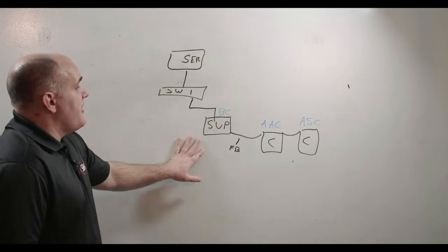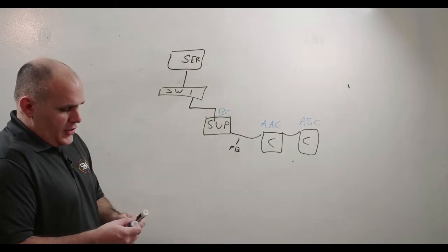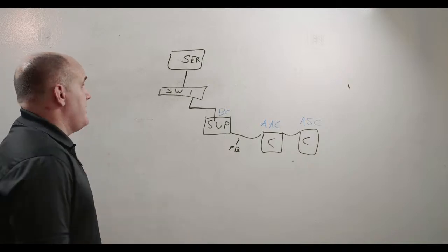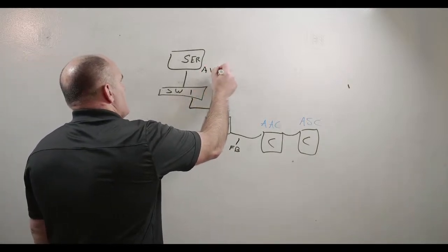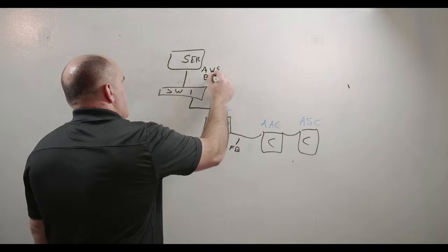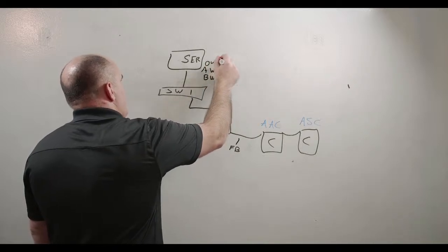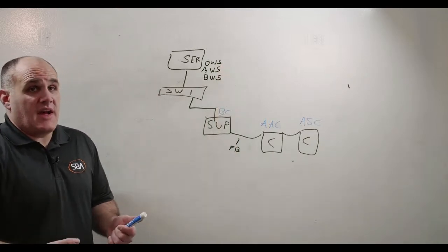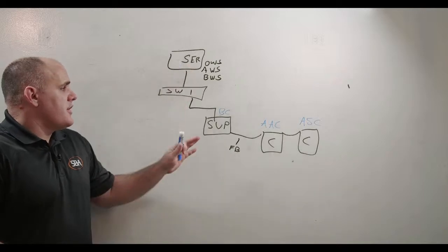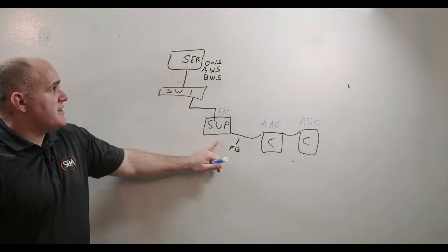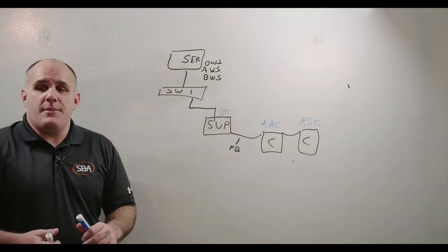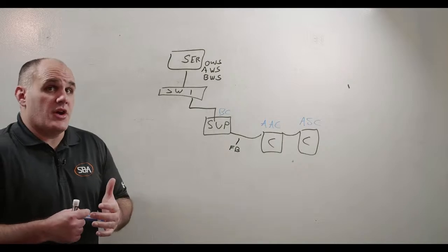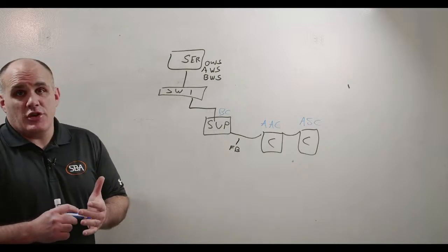Now the supervisory device, the building controller, is going to go to the Advanced Workstation, typically. So an AWS or a BACnet workstation or an operator workstation. There's a variety of acronyms, a variety of BACnet profiles, a variety of types. But the purpose of the server is to take multiple different supervisory devices and consolidate them into one frame of reference, both from a visualization perspective, which is its primary purpose, as well as from a data logging perspective.